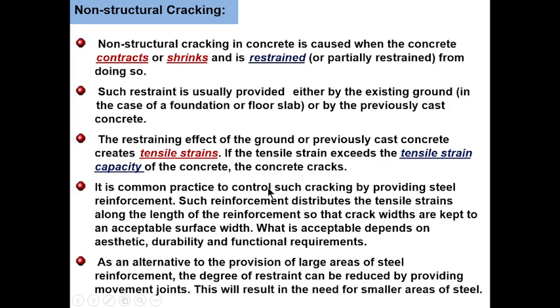It is common practice to control such cracking by providing steel reinforcement. This reinforcement is provided to distribute the tensile stress within that region and avoid the crack, or, although they might crack, the crack will be within acceptable limits for the purpose of aesthetics, durability, and functional requirements.